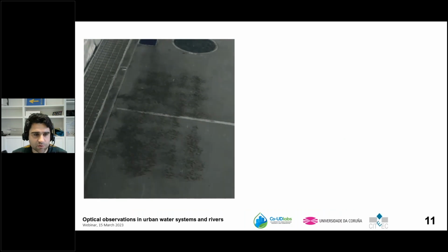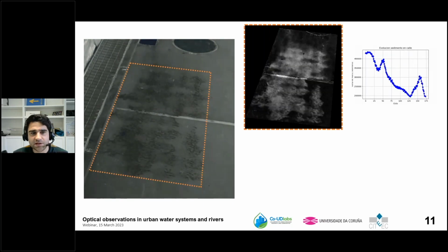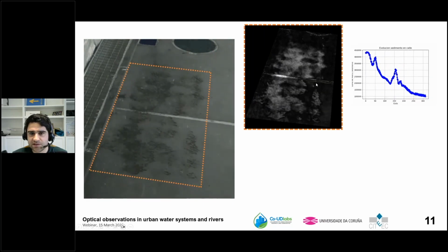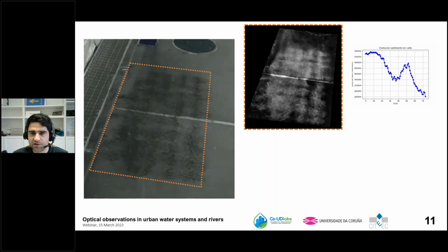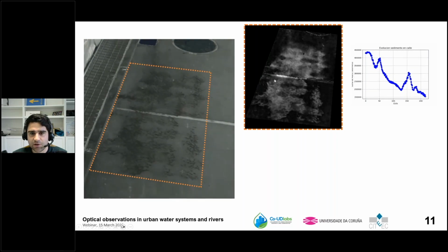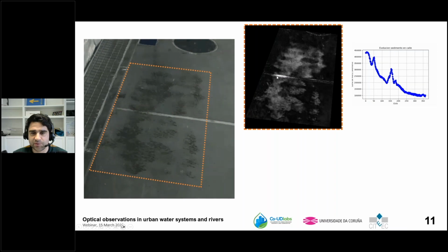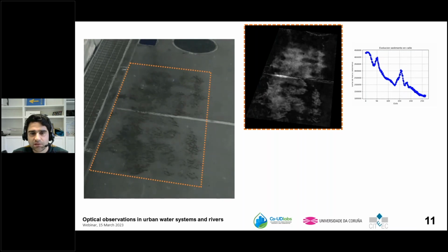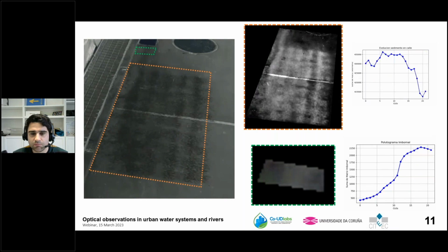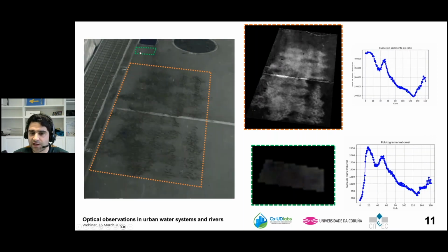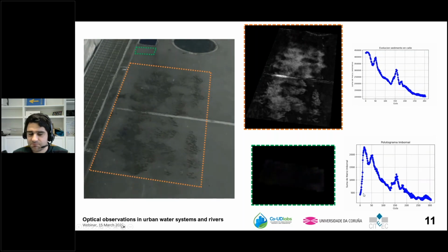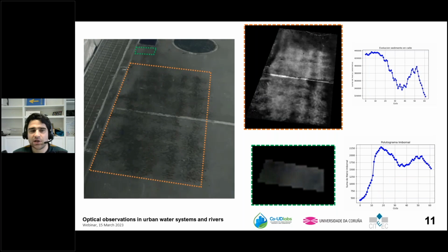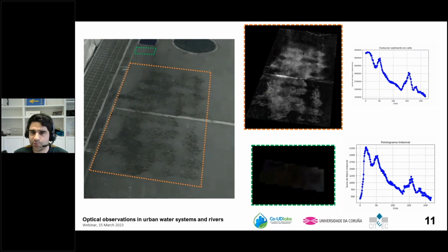In this experiment, we have also recorded the washing of the sediment itself, and we are starting to estimate first the amount of sediment that still remains on the surface during the experiment, just by seeing how the gray color of the image varies regarding an initial point. And then we are also trying to get some turbidity pollutograph at the entrance of the gully, with the same technique. The preliminary results look good, but now we want to compare with experimental data of turbidity at this entrance.